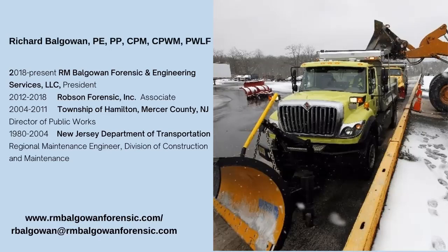One of the critical components of that best practices manual is the use of pavement temperatures. There are many, many times where you'll see it snowing and the roadway won't have any snow on it. It will be black if it's an asphalt roadway. And that is happening because the pavement temperature is not at or below freezing, so the snow will melt. I've experienced many storms where that has happened. That's continued for the entire storm event, and there was absolutely no need to apply salt anywhere because the pavement temperatures were above freezing. And I've seen many agencies, regardless, still go out there and apply salt unnecessarily. So being able to know what the pavement temperatures are when you're applying chemicals is very, very important.